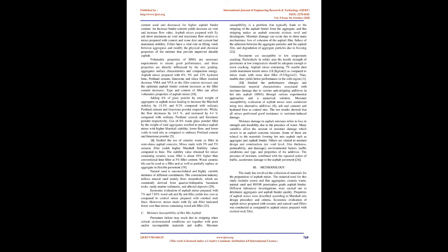7. The optimum asphalt content is the average of asphalt contents that meet optimum stability, maximum unit weight and 4% air voids. By using different percentages of glass waste of 0%, 5%, 10%, 15%, and 20%, the optimum binder content was found to be 5.75%, 5.615%, 5.35%, 5.65%, and 5.68% respectively. 13. Using rice husk ash and slag as filler material in asphalt concrete mixes yields nearly the same Marshall properties as compared to conventional crushed rock filler.